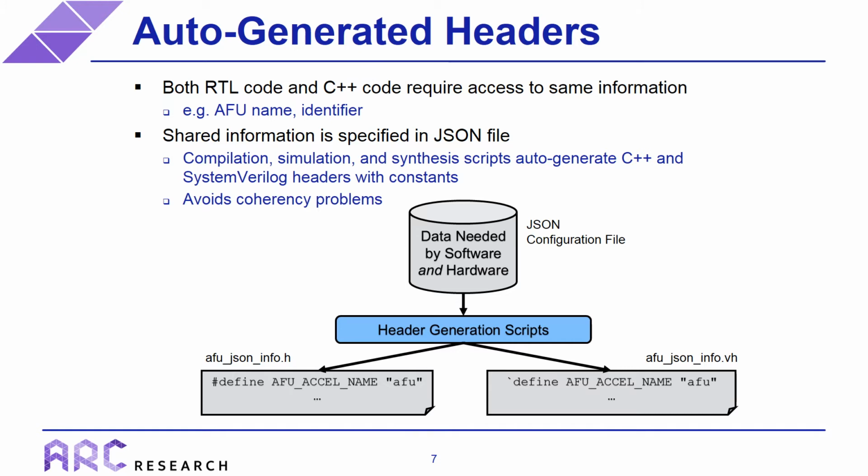But that can lead to kind of nasty coherency issues because say you change the identifier, you change the name, or you change some other shared information. Well, if you change it in the header file for the C++ code, but forget to change it in the RTL code, that's going to cause problems and vice versa.